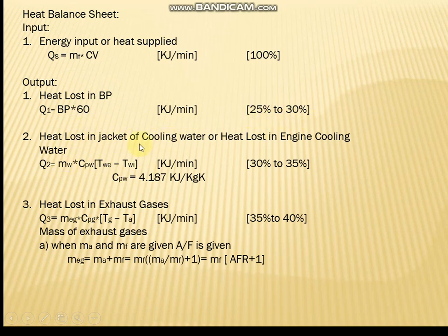Heat loss in jacket cooling water or heat loss in engine cooling water. Some books use jacket cooling water, some books use heat loss in engine cooling water. So that is mass of water, CP of water, and temperature difference of water. The value of CP is 4.187. This value comes out to be 30 to 35%. So Q1 percentage is obtained as Q1 by QS.